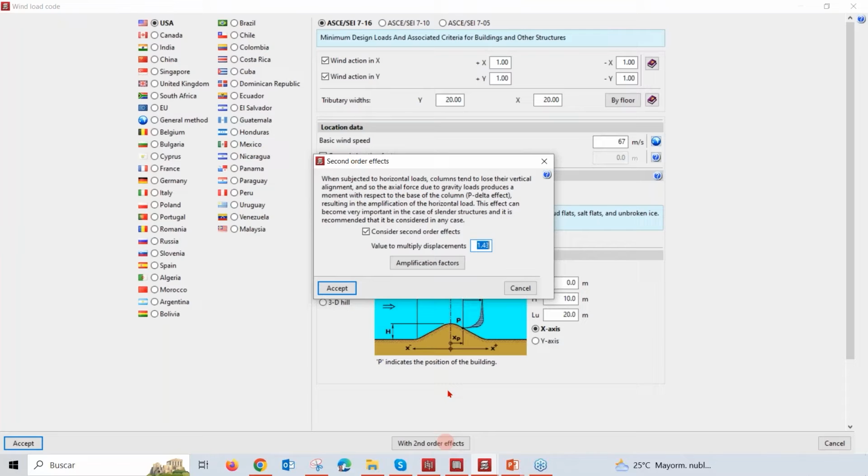That means that we need to go into the elastic nonlinear analysis. The structure itself is going to have some deformation, especially columns, and perhaps some cracks. So we have a simple method called the P-delta effect.